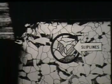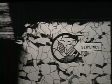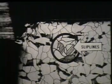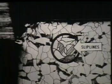In order to clearly see the slip lines that first form during machining, the action must be stopped to study a few specific grains. At the time of the tool's first contact with the specimen, the grains encircled do not contain any slip lines. As the tool progresses a very short distance, actually less than 1 grain diameter into the workpiece, slip lines originate on the surface of the encircled grains, which are a considerable distance in front of the tool. As the tool advances, slip lines appear in more and more grains.